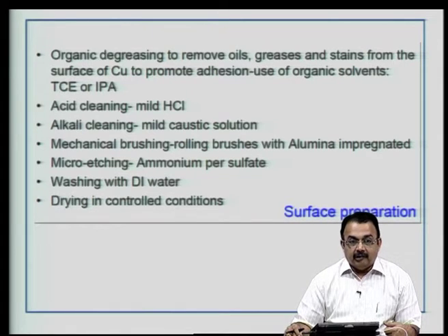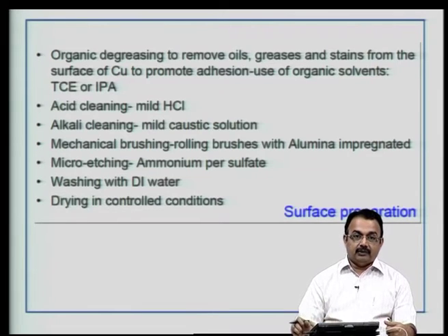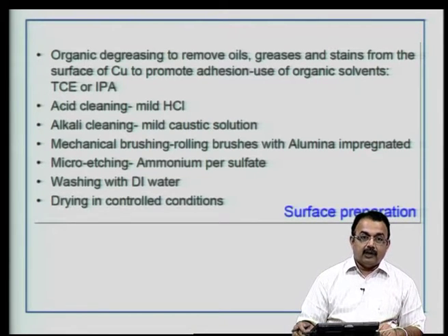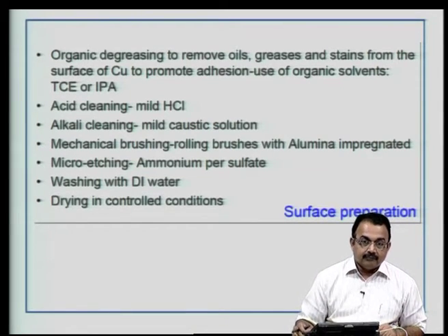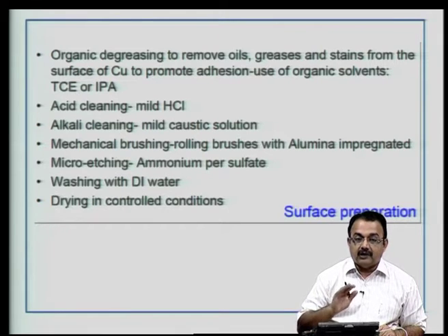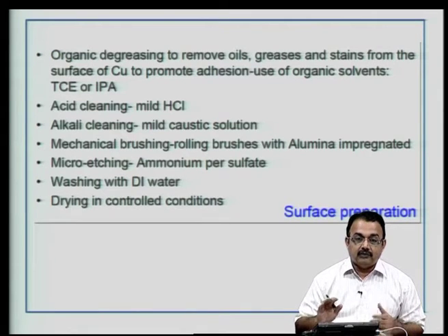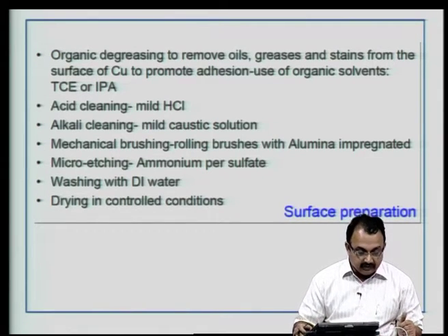Generally, laminates need to be protected until it is used, but if not, nevertheless you have to treat the surface of copper. Now, the treatment is required because we are going to promote the adhesion on the surface of copper. How do we do that? As you know, you are now going to transfer an image onto the copper surface using a photoresist material. So, this photoresist has to adhere nicely onto the copper surface.